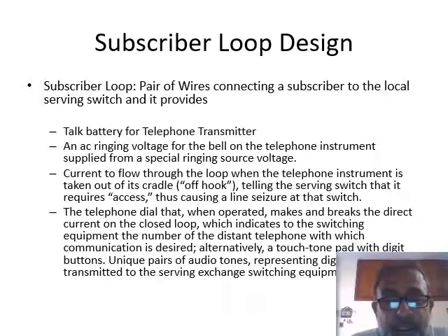Number one, it can be pulse dialed, which you have already seen in the older telephones, in which a round movement is done, and when you dial a certain number, for example 4, the dial is moved round, and when you leave it, the system creates four pulses basically, because it makes and breaks a circuit 4 times.